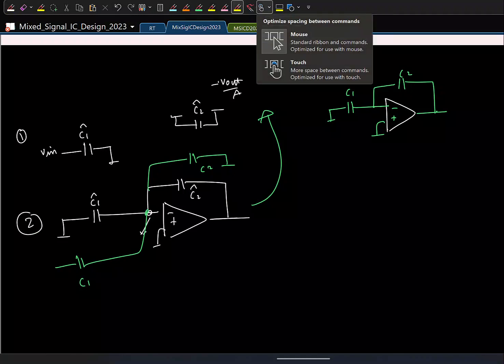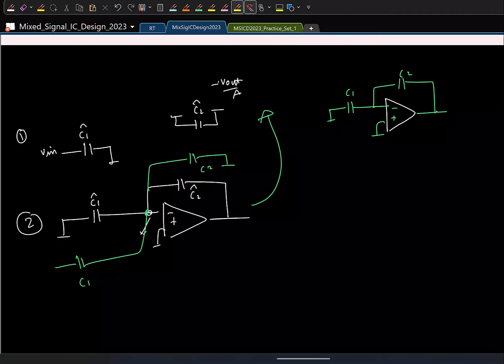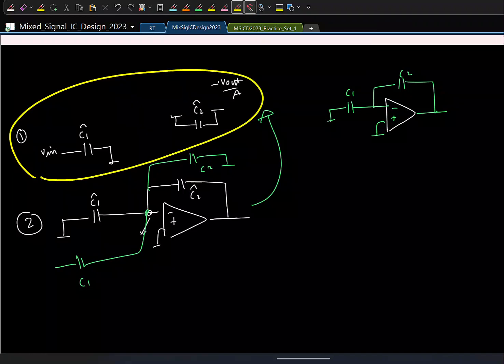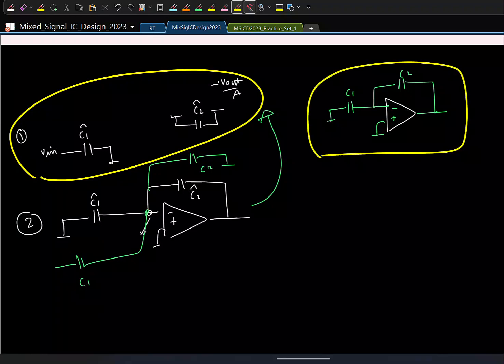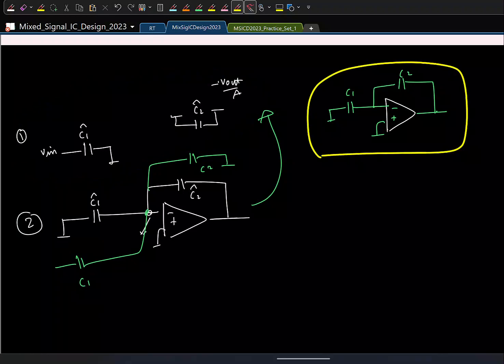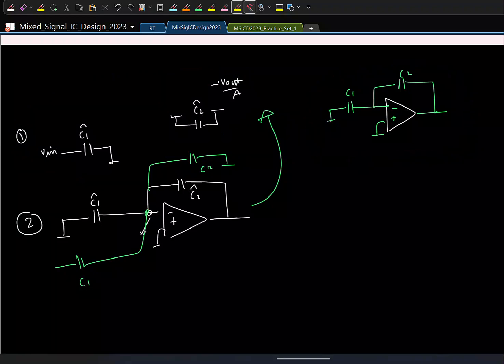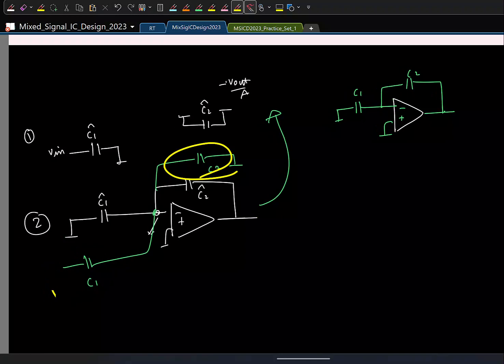In one phase, let's say I call them dummy capacitors. These dummy capacitors must be charged to V in and reset. And in that phase, we'll be doing charge transfer with our actual capacitors. And in the succeeding phase, we'll do charge transfer with the dummy capacitors. And that we are doing to establish the error voltage. And with respect to the error voltage, we are actually sampling our actual capacitors. This is cyclic operation.